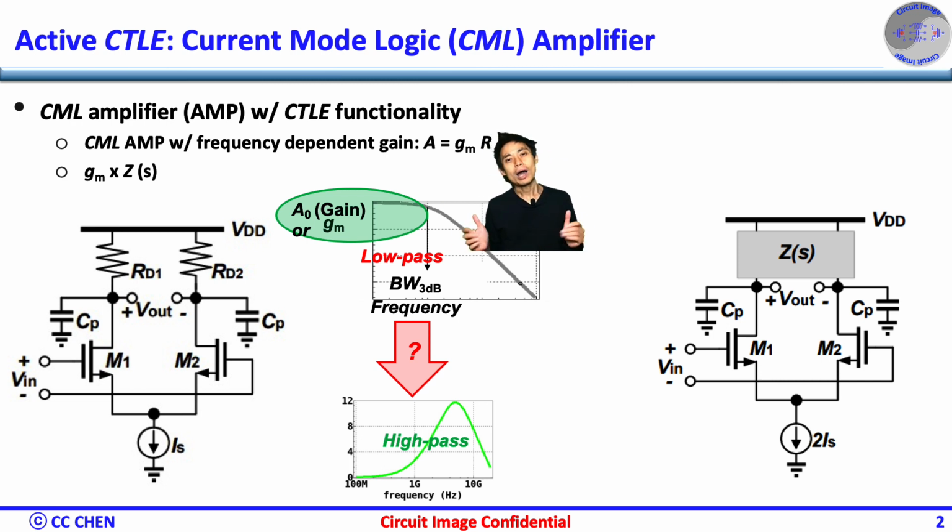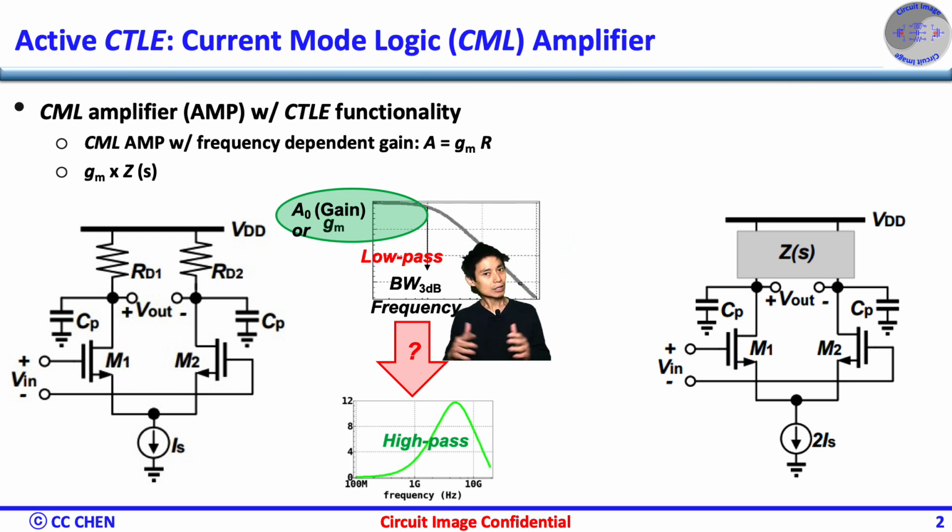But what I mentioned was the DC gain, or the 3 dB bandwidth gain, assuming the Gm value is flat within the 3 dB bandwidth. From Microelectronics 101, you know the frequency response of the voltage gain will be a low-pass response dominated by the output RC time constant.